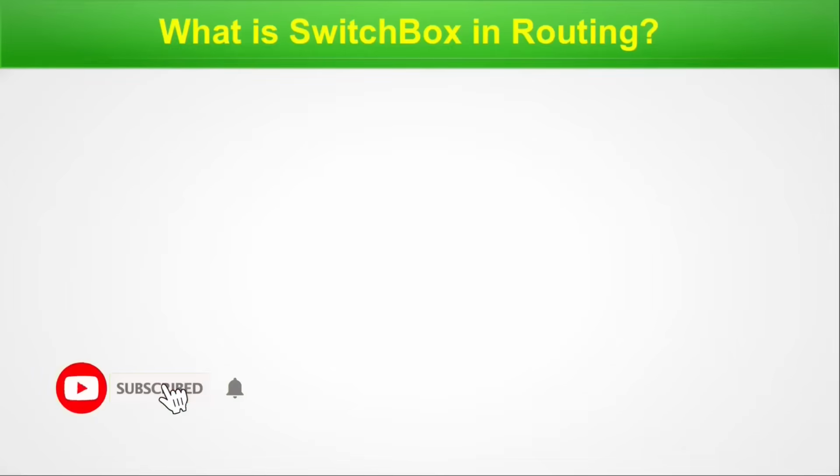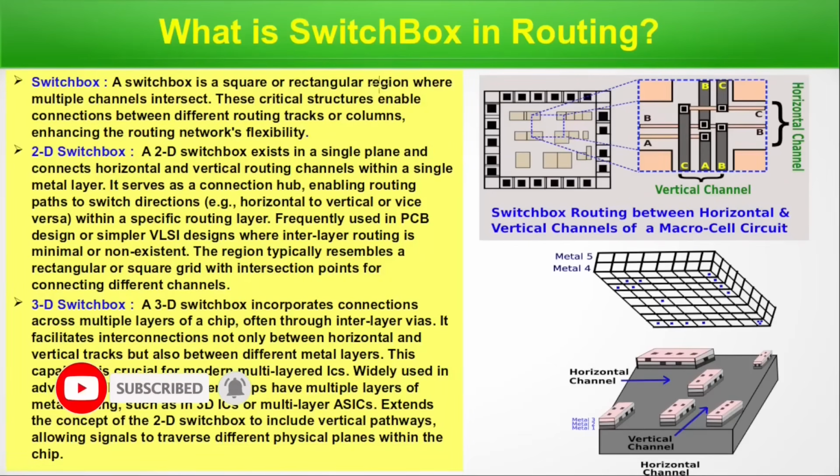What is switchbox in routing? A switchbox is a square or rectangular region where multiple channels intersect. This critical structure enables connections between different routing tracks or columns, enhancing the routing network's flexibility. So switchbox is basically a junction. Multiple channels intersect. That is a switchbox. Here it's shown switchbox routing between horizontal and vertical channels of a macro cell. In this region, this is horizontal channel, this is vertical channel, they meet, and on all sides the routing is done. These interconnects are traveling from one side to the other side.